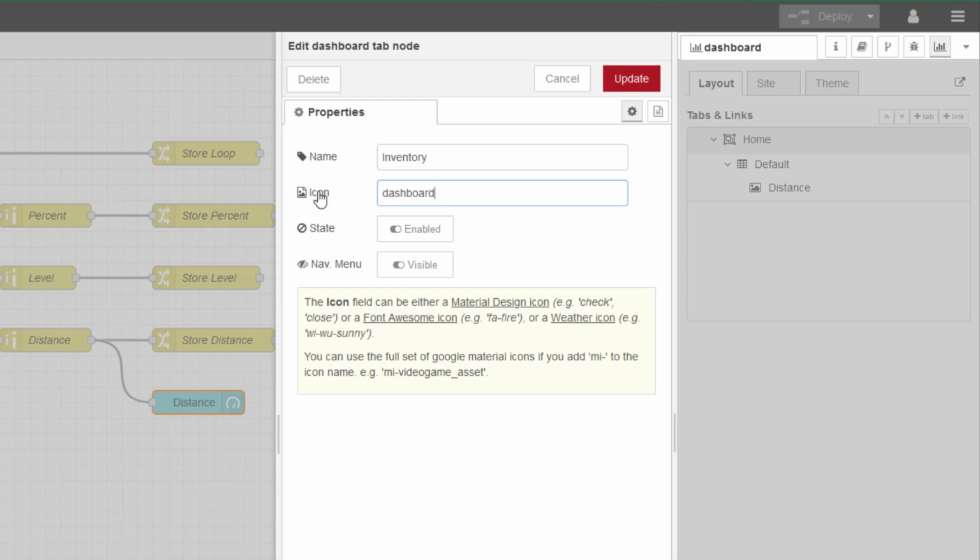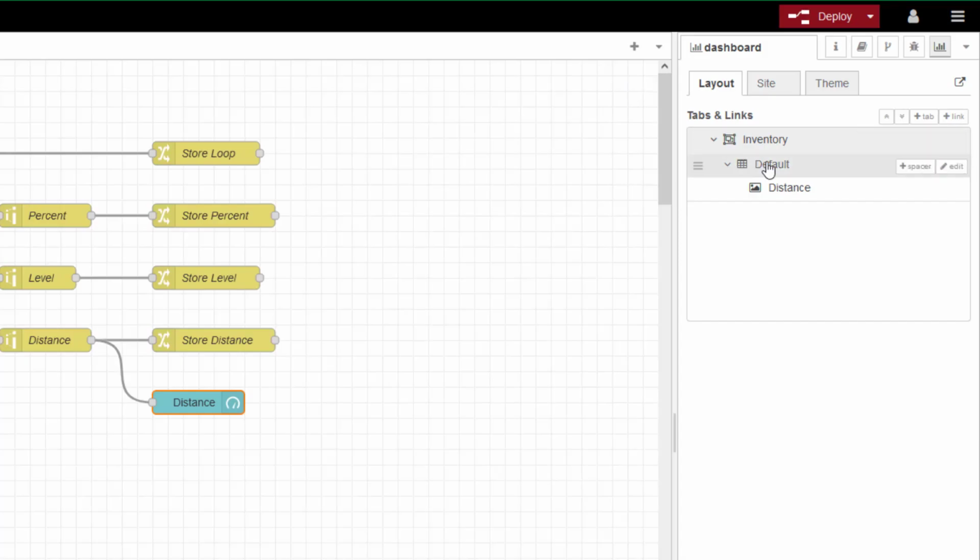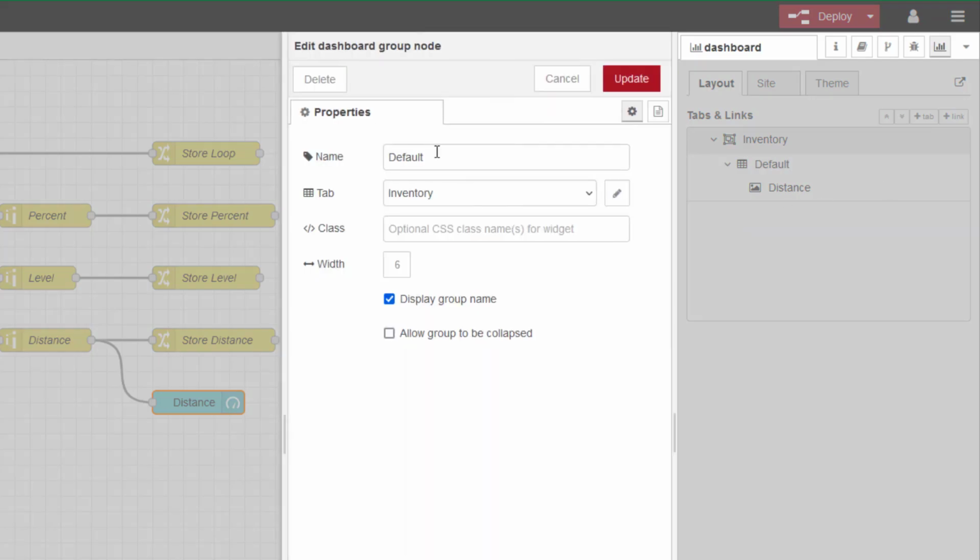I can start playing around with icons as well. I'll come on to how you can start putting icons onto here. We will update that, and then where it says here default, let's edit this, and we will call this vessel 1. Now, because on our input card we can have 4 milliamp inputs and 4 0 to 10 inputs, theoretically if it's just 4 to 20 we can have 4 measurement points, but there is a way to turn 4 to 20 into voltage relatively easy, which we will touch on another video.